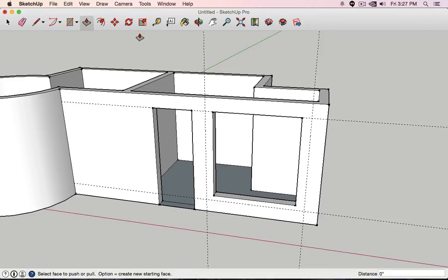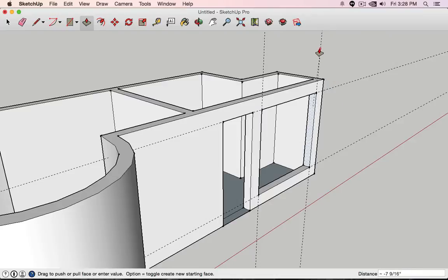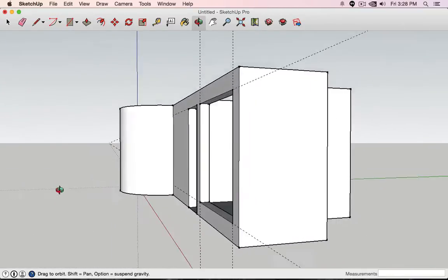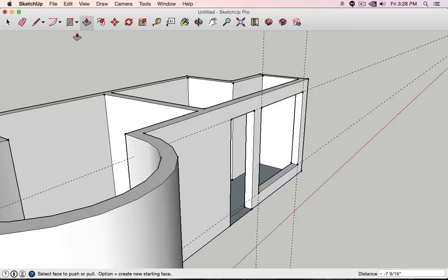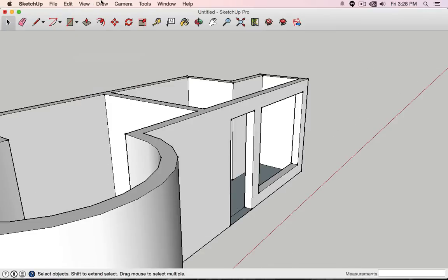Now I can go to the push and pull and, for example, click and see, snap to those guidelines. Snap, and maybe go to here so it doesn't snap to any geometry. Snap there. See, perfectly cut into it. Those guidelines you can delete by clicking on it and then say erase, for example. You can also hide them. You can also hide all guides at once.